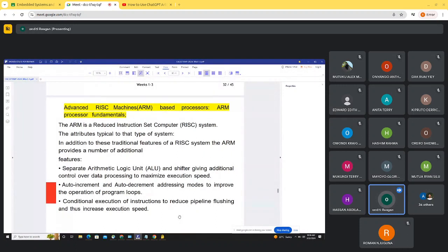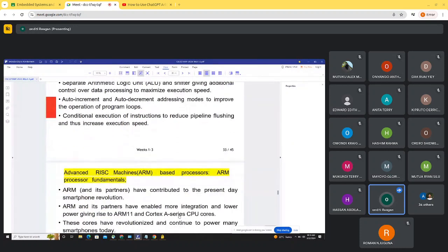If the instruction given to the microprocessor is less than that, and there is no more sitting behind, then that is the only time you realize that this particular type of microprocessor will just execute and clear everything within the pipeline. The other thing I need you to take time and read is more about the arithmetic logic unit within the RISC component, and how you introduce what you call flushing and increase the speed of that type of microprocessor.